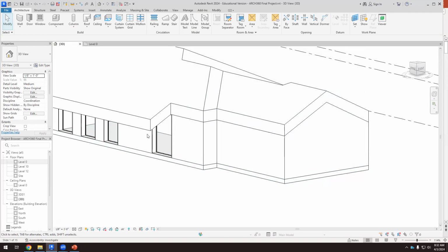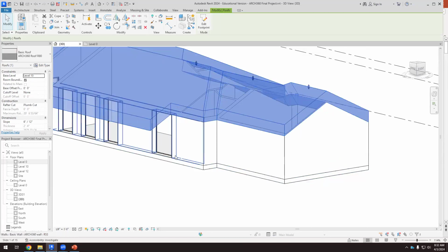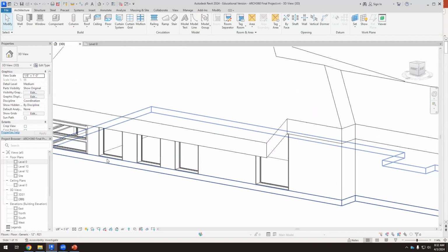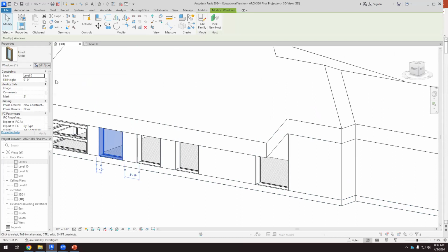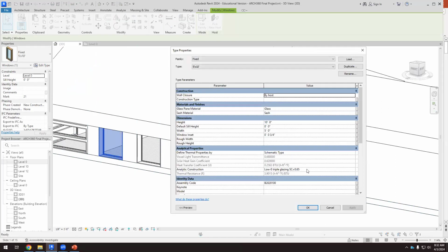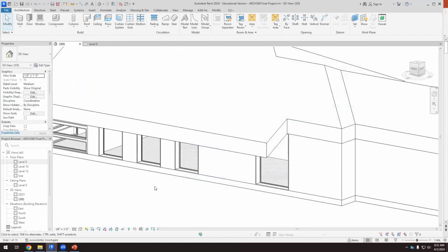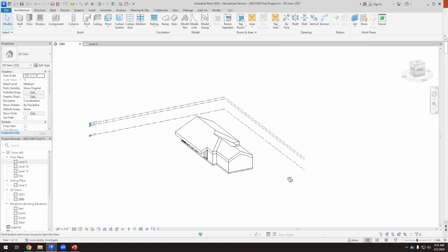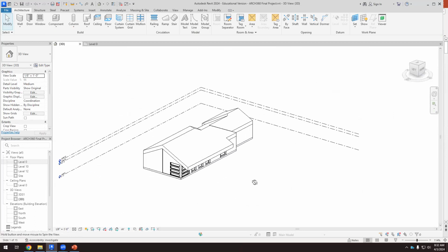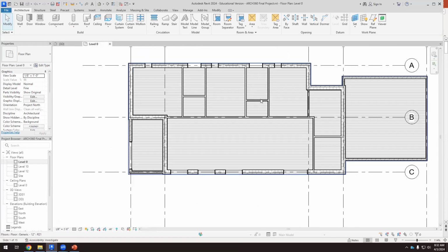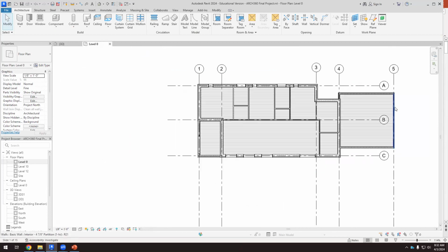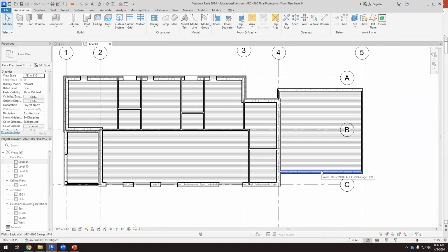Around 50 for walls, around 60 for roofs. I think we have a good envelope. If we select windows, make sure that it's always low emissivity, triple glazing, and all that stuff. Okay. So once we have this, we need windows in every living space. Well, in the garage, we don't need a window, we need a big door.